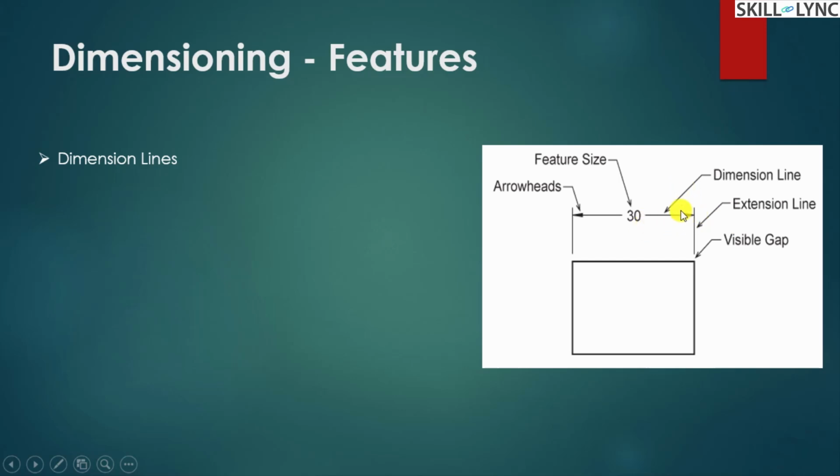and that, along with your extension line, denotes where the measuring object is. Suppose you are going to measure this object, then you have to use these two faces and ensure that between these faces the dimension is going to be 30 units here. So towards that you have the dimension line as well as the extension line.